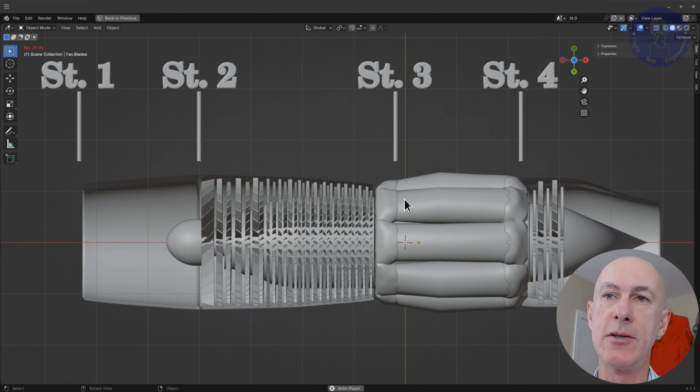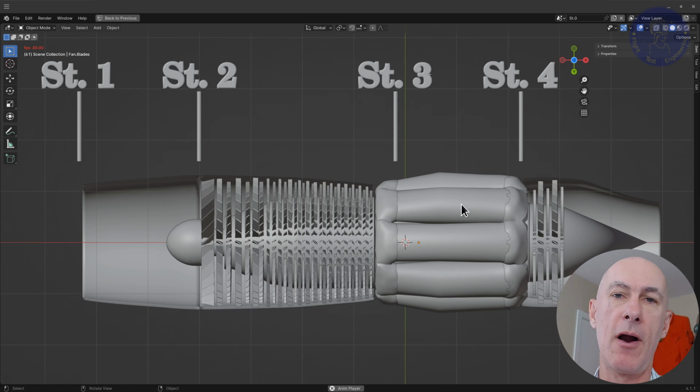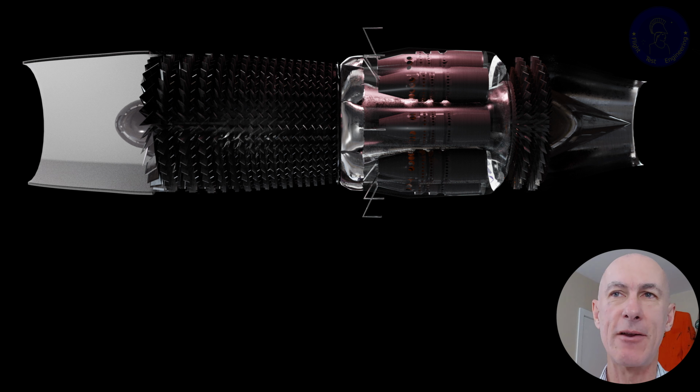In this case, we just want to add fuel to air and burn it in the combustor. Easy, right? Well, there are a few constraints here. Let's look at some of them. I have made the outside of the combustor transparent so that we can see what's going on inside with the liner. First, we can't have the flame extinguished, so the conditions need to be stable here.